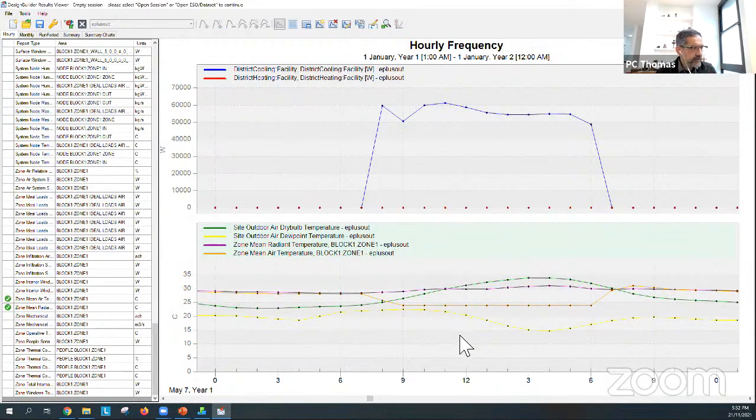But two things you can see. The radiant temperature in the zone is much higher than this air temperature. Okay? And you need to improve the building facade. You need to put insulation on the roof, the walls, you need to put a better window, etc. And the outside temperature peaks around 3 p.m. But the inside temperature might peak just a little bit later, about an hour later. And that's the mass storage of heat, etc.